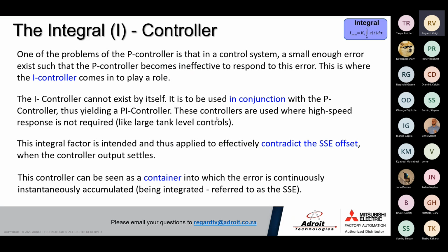Okay. The second most popular will be your PID controller. The third will be your P controller, and then in very, very rare cases you'll have a PD controller, and that would be usually for automation in motion and so on. We have servo motors, but even then, in most of those cases, you'll use a PID, not just a PD.